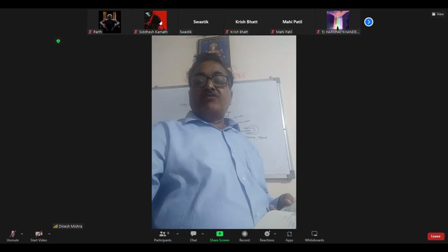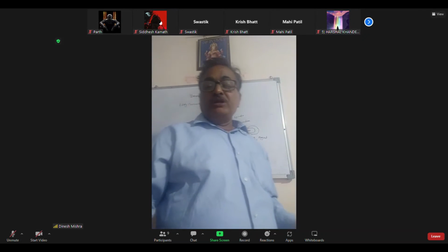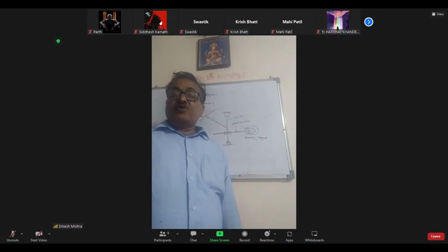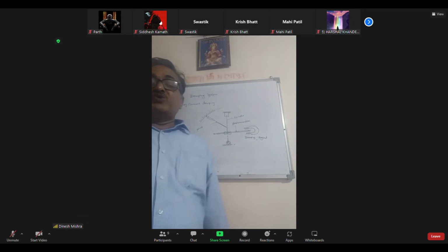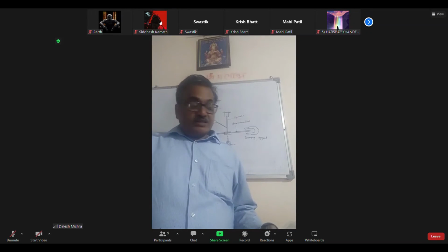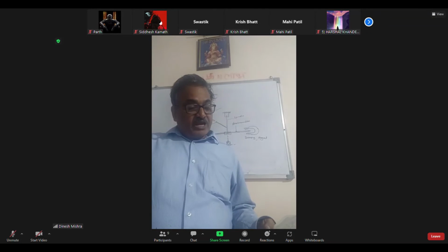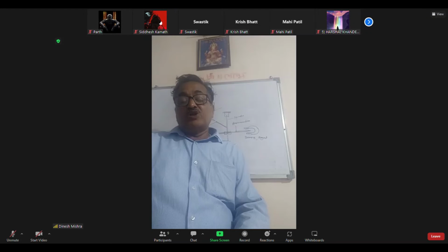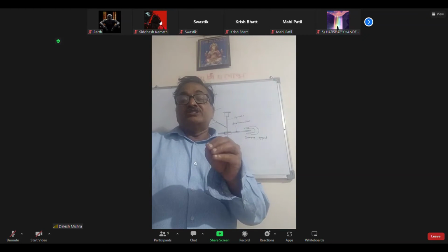So what are the requirements of a measuring instrument? The deflecting force and the controlling force. There are two types of controlling force: spring control and gravity control. Then three types of damping force: first air friction damping, then fluid friction damping, and the third is eddy current damping. By using all these systems, an electrical instrument is constructed.